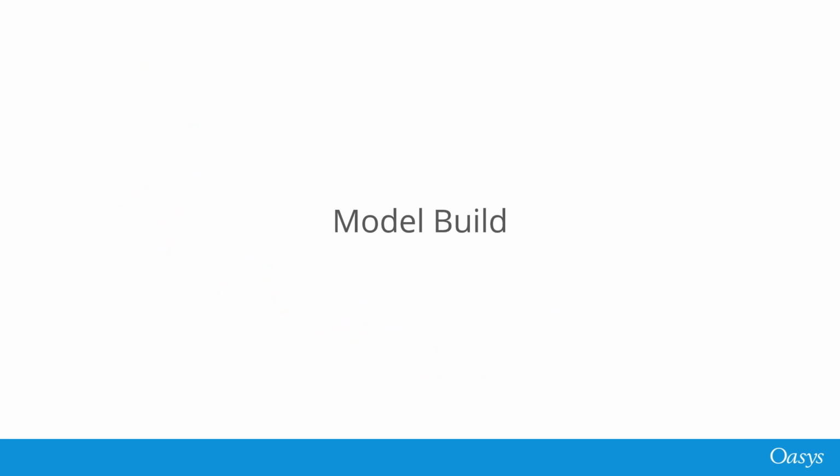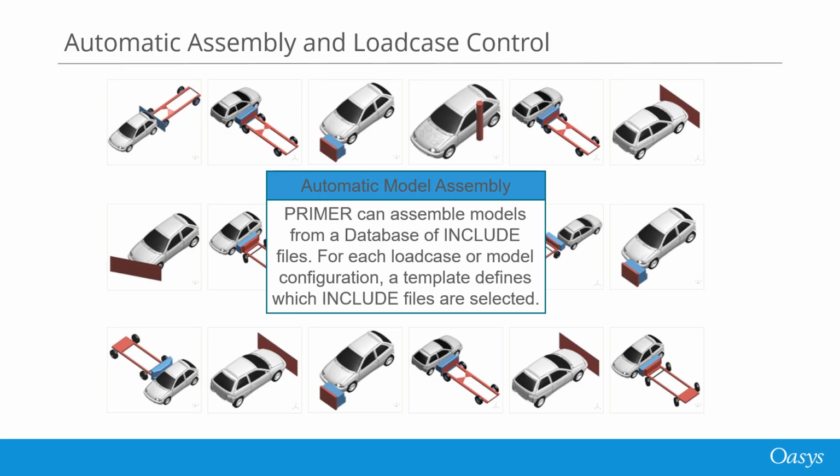Now I wanted to also mention model build at this point. So the model build tools within Primer have similarities to Crash Test Setup, but it's a more general tool for building models. So Primer includes the ability to create a database of include files, and this database can then be used to build models for different load cases using the same vehicle model. So again, it provides a consistent way of building your models to ensure everything is correct in the models that you run.